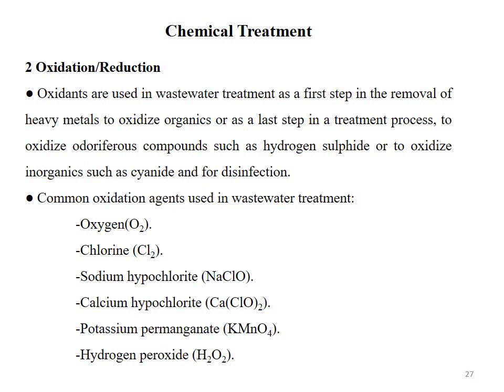Among the chemical treatment, another method is of oxidation or reduction. This is sometimes combined named as redox treatment or redox method as well. Oxidants are used in wastewater treatments as a first step in the removal of heavy metals to oxidize organics, or as a last step in a treatment process to oxidize odoriferous compounds.